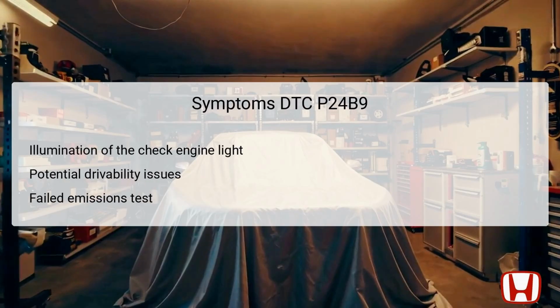Symptoms associated with DTC P24B9 often begin with the illumination of the check engine light on the dashboard. This warning signifies that there is a problem within the EVAP system that requires attention. Drivers might experience drivability issues that manifest as rough idling, engine hesitation, or even reduced fuel efficiency, depending on how severely the EVAP system's functionality is affected.